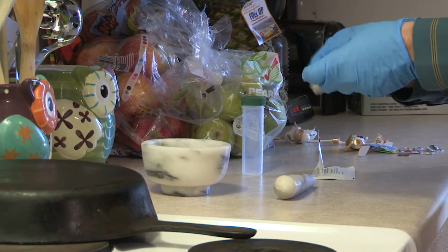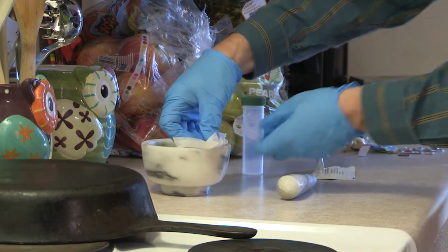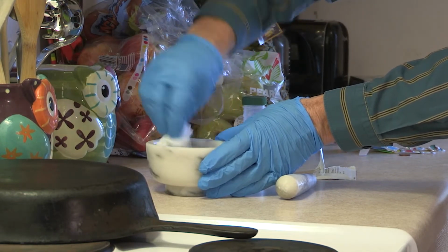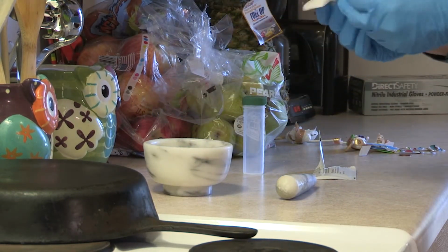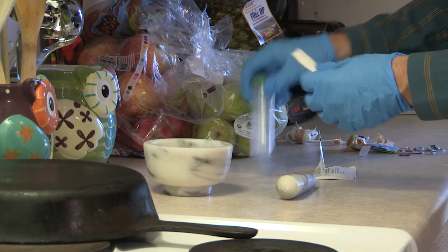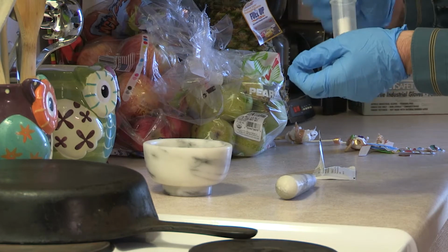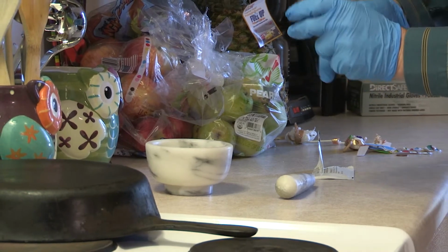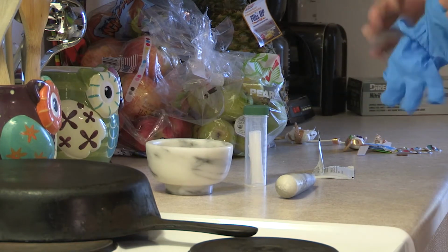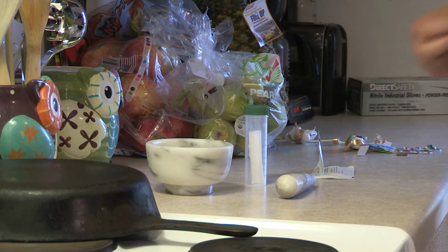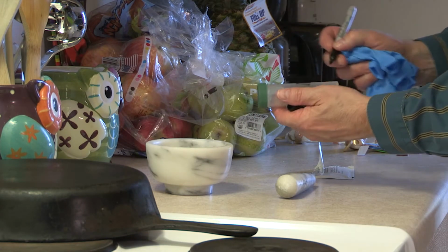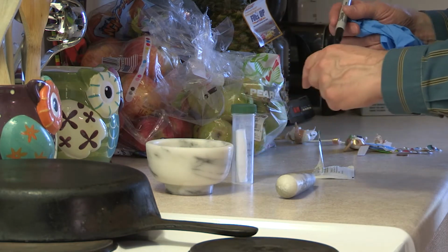Remember that the U.S. Food and Drug Administration, FDA, sets the allowable level of lead in food, candy, powders, and cosmetics. Refer to current FDA regulations for these limits. When investigating because of a lead-poisoned child, pay close attention to bathtubs, sinks, or other household fixtures that have porcelain or enamel glazed finish. This glazing may contain high levels of lead and could be a possible lead hazard, especially if the glazing is chipped, scratched, or worn.